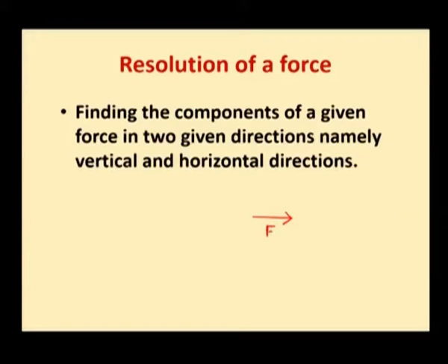Resolution of force is finding the components of a given force along two directions, namely vertical and horizontal directions. Suppose you have an inclined force acting like this. Resolution is nothing but finding the components of this inclined force along two directions, namely the horizontal direction which is x axis and the vertical direction which is y axis.